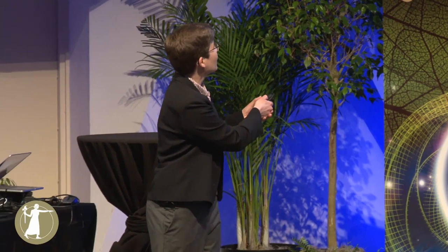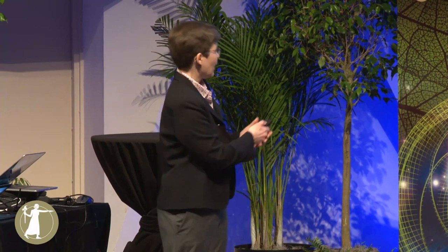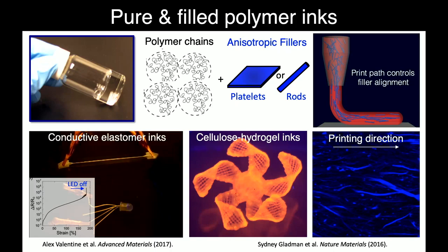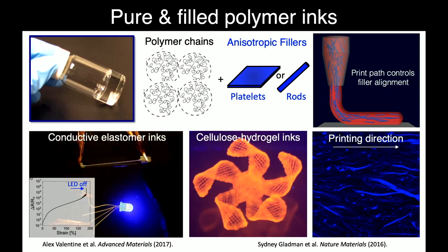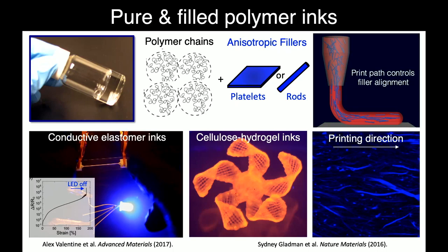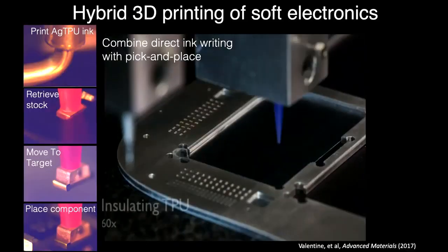So here is an electrode that we've printed on a pure polymer substrate. You can see that as this is stretching, the LED light that it's connected to is going to start to dim. And ultimately, when we get to a strain of about 200%, we'll break electrical contacts between the particles and the light will go off. And then as we relax this back to a zero strain condition, it then, of course, reconnects electrically. And what's connecting really are these contacts between particles that are able to slide as we stretch and reconnect as we come back. So what can we do with something like that?